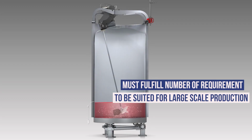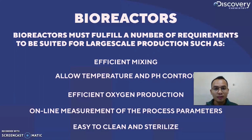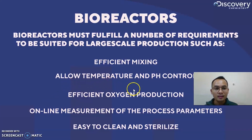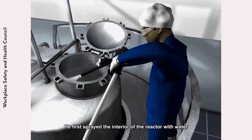Bioreactors must fulfill a number of requirements to be suited for large-scale production, such as efficient mixing. Bioreactors must allow efficient mixing in order for the microorganism not to be under mechanical stress. Like I said before, if the microorganism is under mechanical stress, it may cause damage to the microorganism itself. The second requirement is that it must allow temperature and pH control, and the third is efficient oxygen production in the bioreactors. The next one is online measurement of the process parameters, and the last one is that it needs to be easy to clean and sterilize, which means after the fermentation process has occurred, the bioreactor needs to be cleaned. So easy-to-clean bioreactors may be the best suited for large scale production.